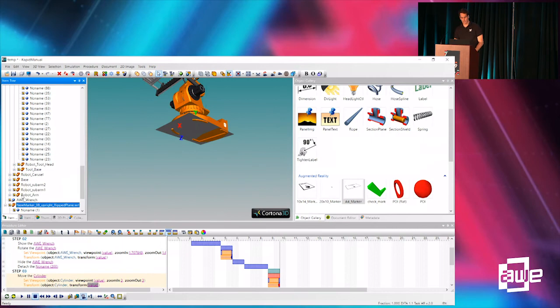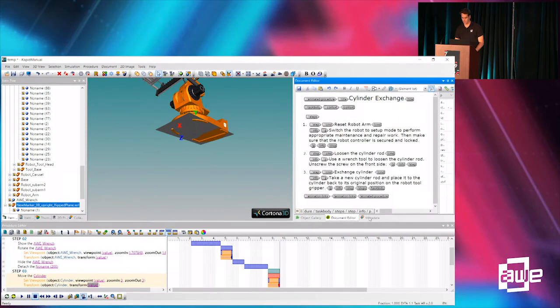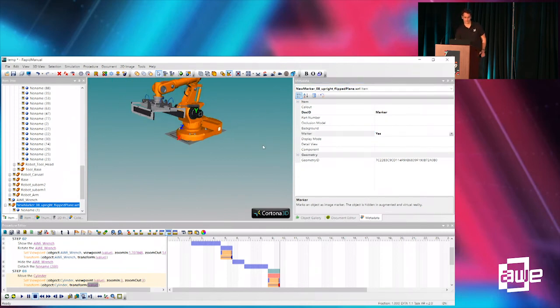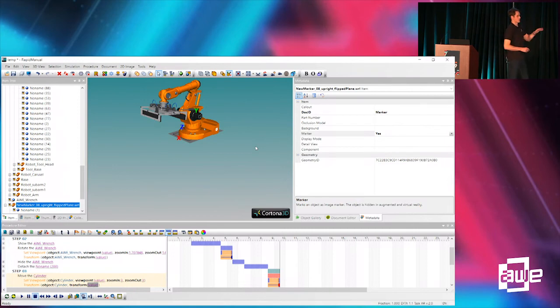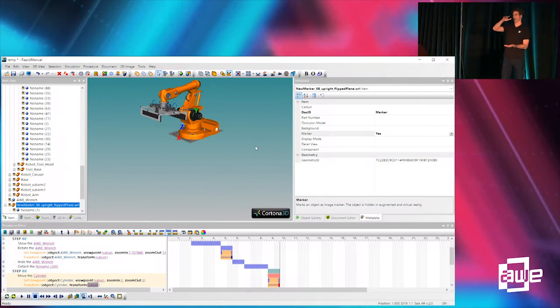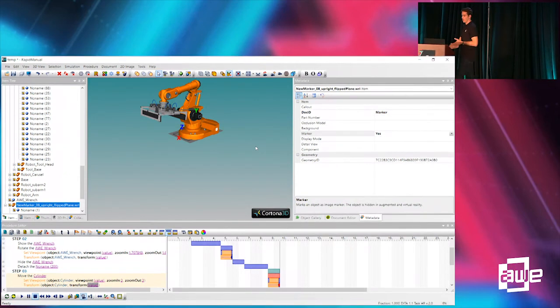I'm going to tell the augmented reality mobile viewer that this component is actually a marker. So I'm going to name it like this, a marker, and I'm assigning a metadata marker. What does this mean? My mobile viewer knows that this component is just used as a marker to overlay the 3D animations on it. It won't be displayed in augmented reality, of course.